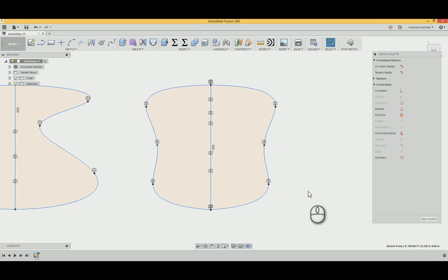Okay, because it's not letting me click more than one thing when I try to do that. Oh, you know what? It has a constraint of some sort. Right. When something doesn't behave the way you expect it to, it probably has some kind of constraint already. You inadvertently, yeah. So you hit the point, you hit the second point. Right, and then you hit the mirror line. Okay, now they're symmetrical. Got it.